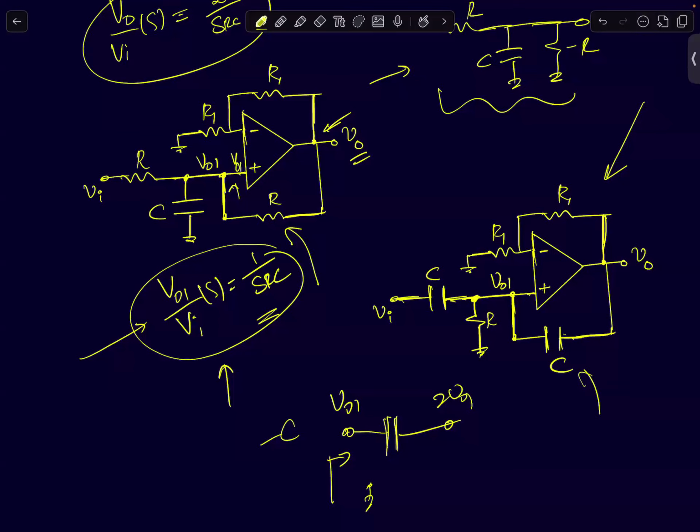Okay. So here, if you see, right, I didn't use 2 capacitors. I just used one capacitor to build a non-inverting integrator. I don't have 2 capacitors here. It's just a single capacitor. Differentiator, yes, we have 2 capacitors, but the integrator has just 1 capacitor. I'm just showing another possible realization of a non-inverting integrator using the idea of negative resistance.